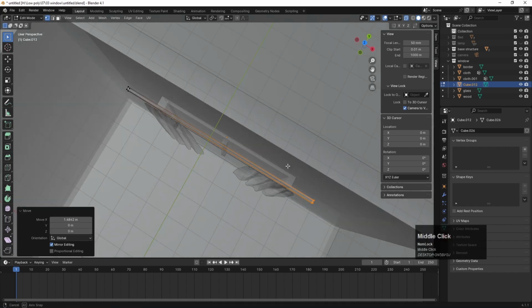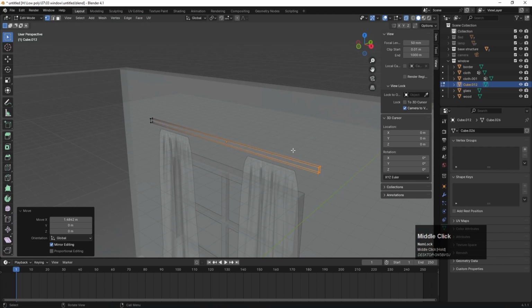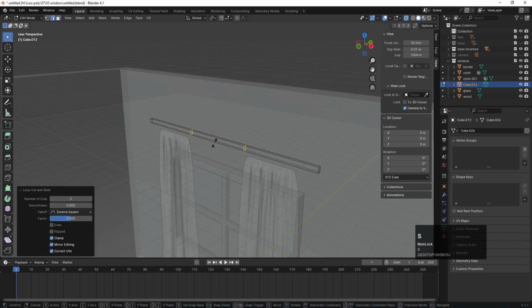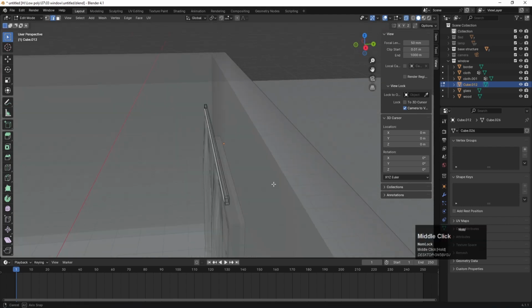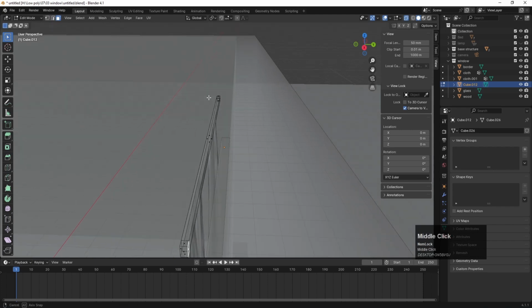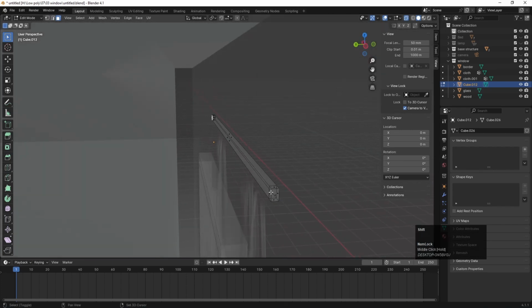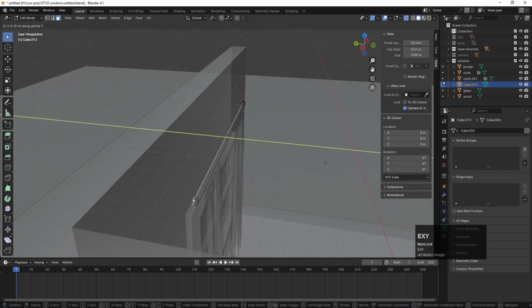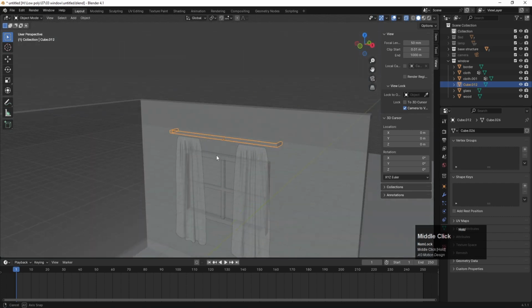Like this. Okay, now press 3, hit A, and press Ctrl R, and create two edges over here like that. Then press S X and let's scale it like this. Okay, then after that we will select this, press 3, we will select this portion. Similarly, we will select this portion by holding shift and press E, X, or let's say Y, and we will try to bring them up to this. Okay, not too much, but up to this only, and press tab like this.